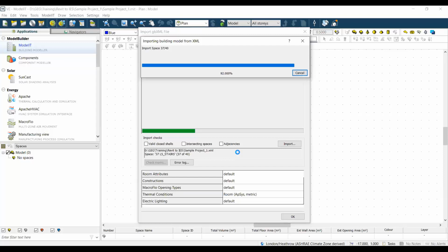And for this top one, if we have traced the outer face of the wall, you might see something protruding out of this particular profile, like it's cantilevered a little bit. To be particular, it's 50 mm cantilevered because that's how much the outer face is away from the center line of the wall. So you'll have that unnecessary green protrusion on the profile of the roof. So that's not what we want. So we want something that looks like this.